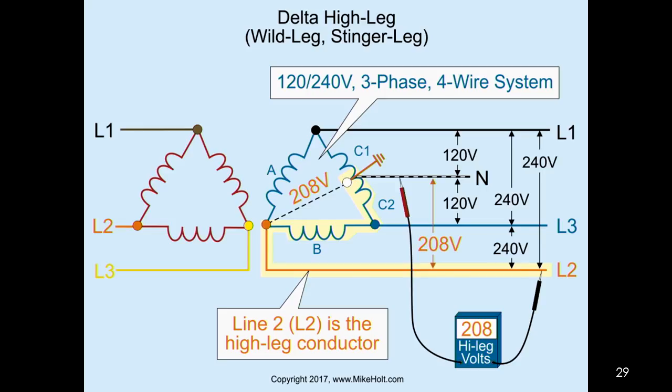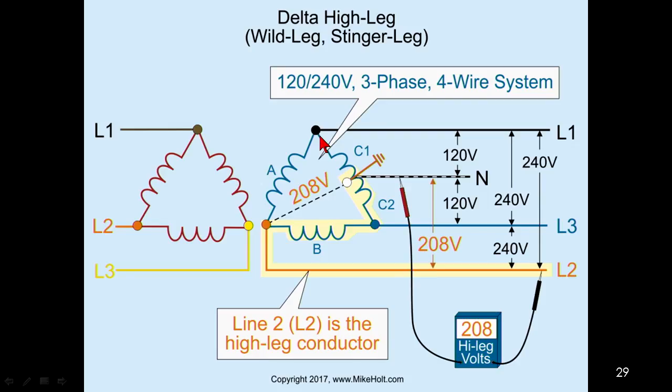Yeah, real quick. If that's a 30 kVA transformer, a really easy way of looking at it: A is 10 kVA, B is 10 kVA, C is 10 kVA. So by definition, you can only have 10 kVA worth of the 120 volt loads. But the problem is, if you have line-to-line loads when you do that panel schedule, you better not put any line-to-line loads between line 1 and line 3. Exactly. Because you better make sure you put them on line 1, line 2, and line 3.